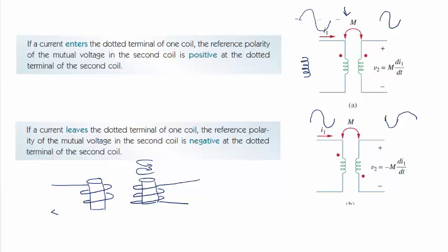So I'm going to go back for a moment and talk about what your textbook is calling the mutual voltage, and it's really the induced voltage. For example, the presence of this secondary coil induces a voltage on the primary coil and vice versa. So this term right here is an induced voltage. A voltage is induced on the secondary side due to the current on the primary side, because it's I1 times this mutual coupling M. But I'm going to talk about it a bit more.